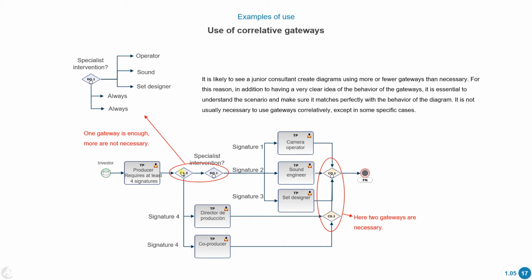But we could see another possible scenario would be to use a DO gateway. Instead of using two gateways, we could actually use one, because the DO gateway could perfectly activate these two outlets down here, and besides, one or more of these outlets up here. Okay, so in this scenario, we could use a DA and a DO, or we could just use a DO. If the DO is correctly configured, it could work perfectly.